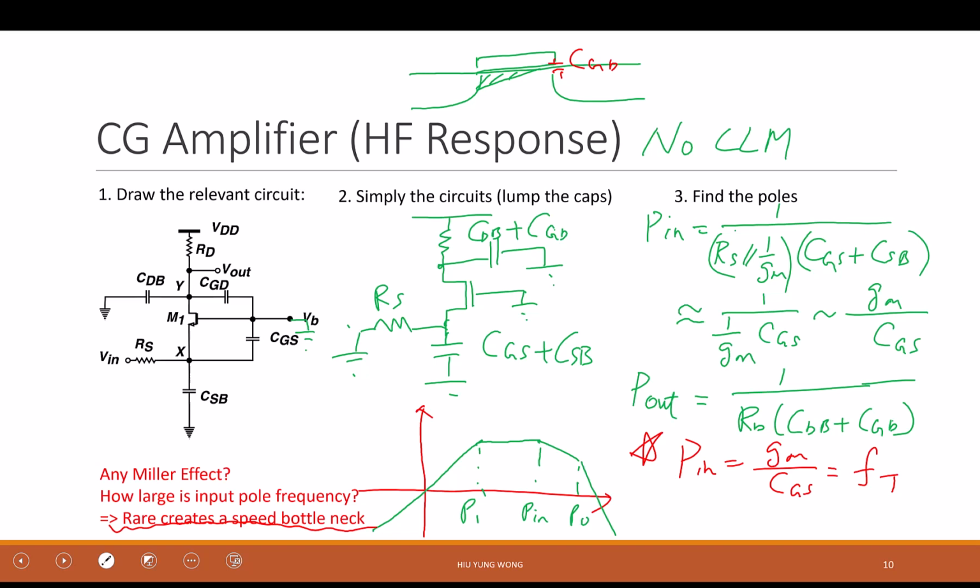If you go to the industry, when people talk about a circuit, we don't only look at the DC and don't only look at the gain. Now you know very well I need to consider what is the input impedance, what's the output impedance, whether it's positive or negative gain, and then, of course, the power consumption, is it easy to lay out, and then its frequency response.